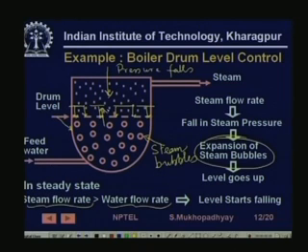So, you see that here we have a non-minimum phase response, that is, in the long range the volume should start falling, but in the short range it will go up. This is non-minimum phase behavior. This is shown in various other cases, in aerospace plants also such a thing is shown, but anyway.